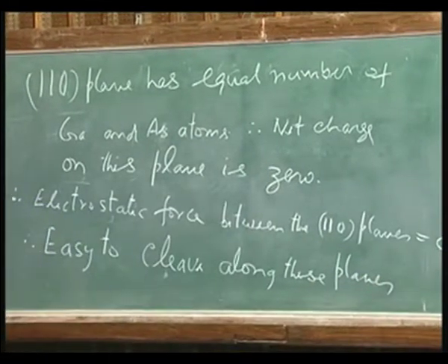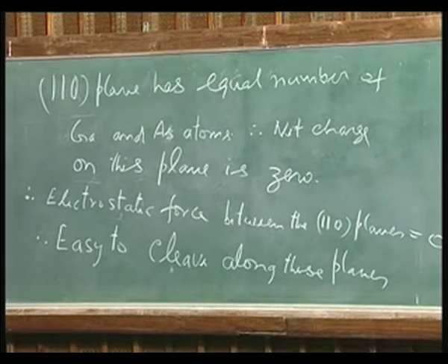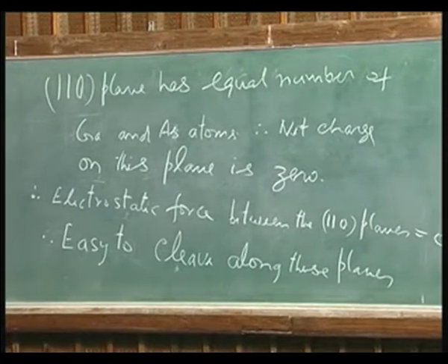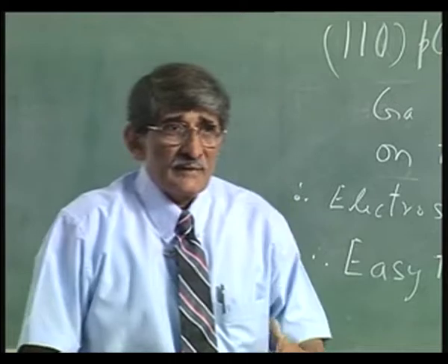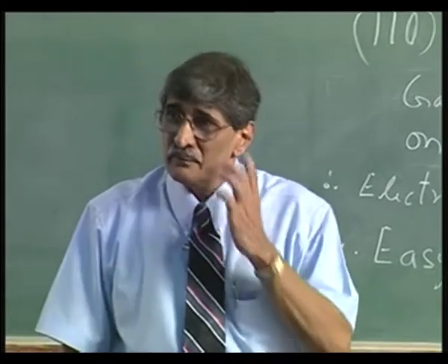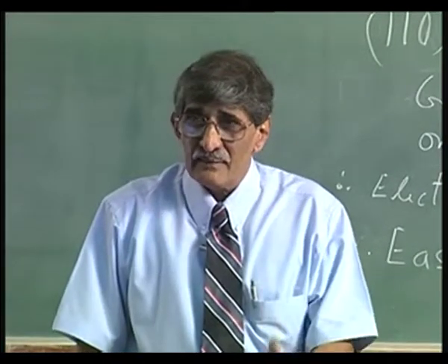Therefore, it is easy to cleave along these planes, because that is the key thing. Therefore, whether it is gallium arsenide or indium phosphide, the cleavage plane is 110.